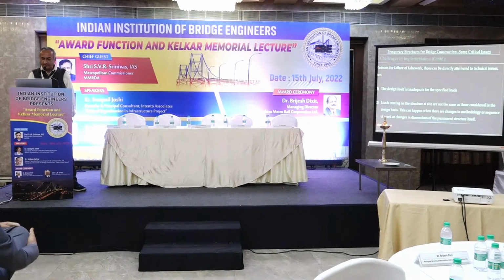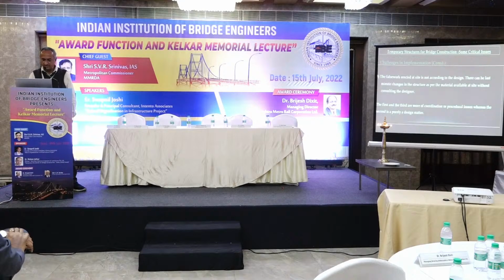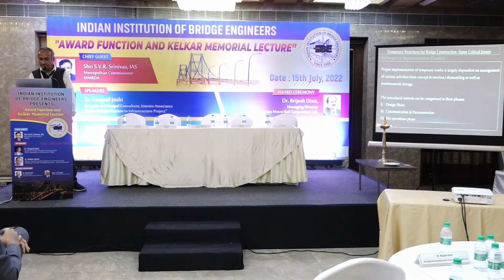So the reasons for failure of falsework, according to him, were that the design itself is not adequate, loads coming on the structure are not the same as what was designed, there is a difference in what is happening at site, and the falsework erected at site is not as per design. So these are the same causes which were found in the later research done by Baptista and others, which I presented.